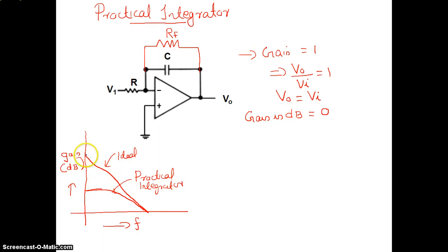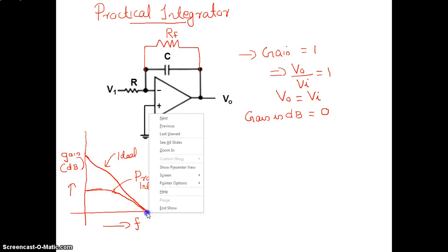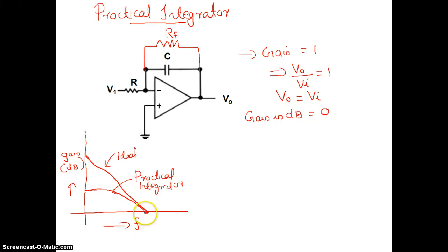The initial high gain here we are limiting, it is a straight line like that; when I draw it, it becomes somewhat twisted. So initial gain we have limited over here. At the point where the gain in dB is equal to 0, the actual gain is 1, and the output is equal to your input.